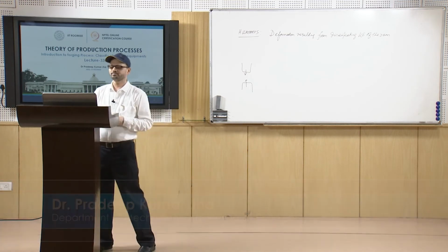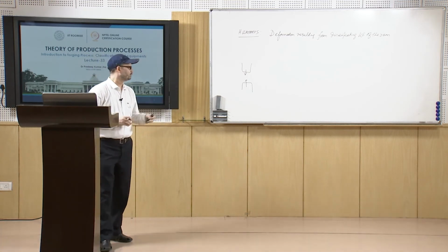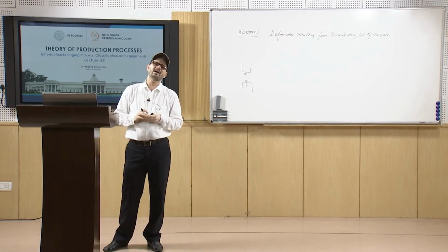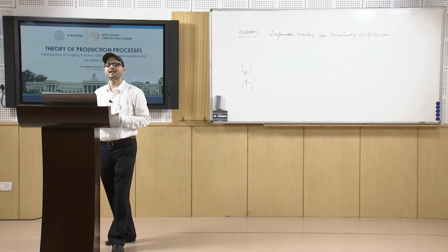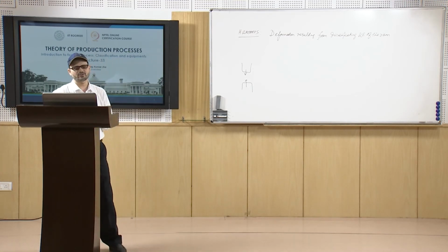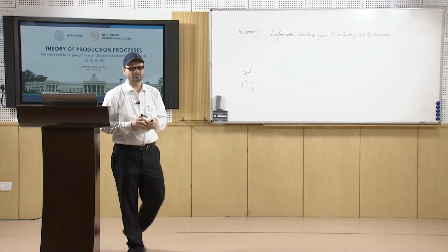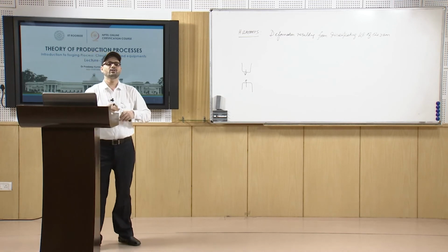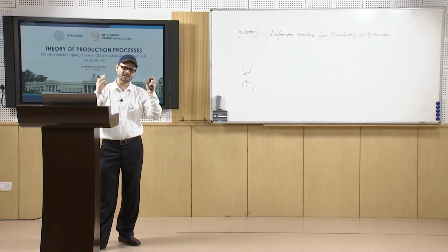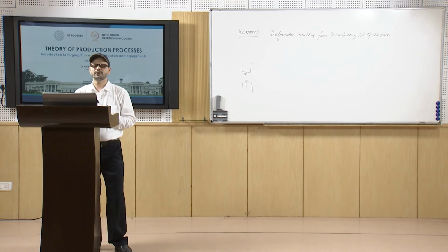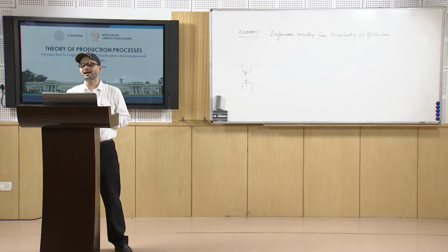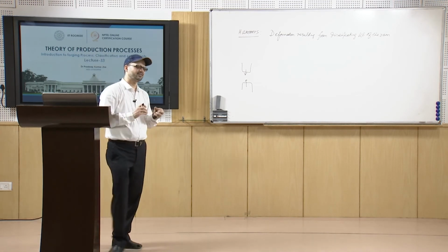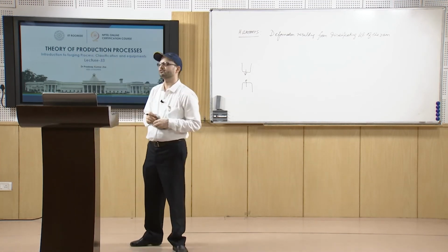Now, you have many operations where, if you reduce this, you get the impression close to the final one, and you have flashless forgings or precision forgings because of quite low forging loads and low temperatures. That is precision forging. You have the example of isothermal forging also, where the die and the metal are kept at a similar temperature.